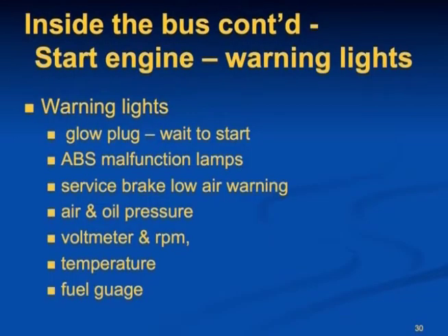As we continue inspecting inside the bus, let's start the engine. Before you start the engine, make sure the glow plugs, also known as the wait to start light, goes off before attempting to crank. In colder weather, you may need to turn the glow plugs on and off several times before you crank. Anti-lock braking system.